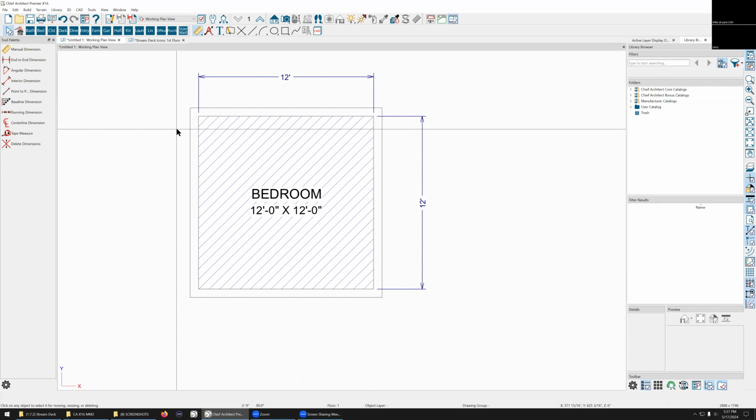That's wasted money. So you're making it like 12'7", whichever direction you go with your joist. No matter which way you go, you're throwing away 1'5" of joist on each joist.